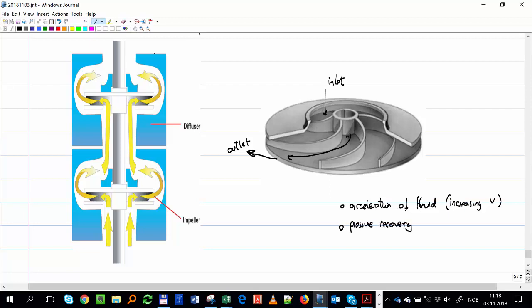Because the energy, we cannot keep it in velocity, because that means that every stage the velocity will be higher and higher and higher. And what does it mean? More friction, more erosion, more problems. So a smart way is to transfer energy and then recover it to pressure. And the way to recover to pressure is I just expand, right? Here I have high velocity and low pressure, and then when I come here, I have high pressure and low velocity. And I'm ready for the next stage.